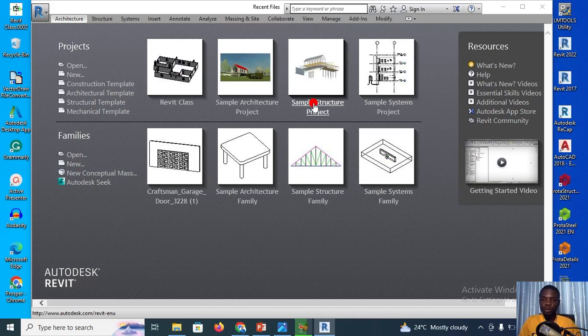But Revit is good when it comes to architectural modeling. All right, Revit MEP is another aspect for electrical engineers who want to design. When you are designing a high-rise structure or a big structure, you need to do the electrical plans, your AC layouts, your lightings, your socketings, and everything. Revit MEP helps you do that. All right, that is what we have here. Then under that, we have what we call families. Families are custom tools or custom components that you can create.